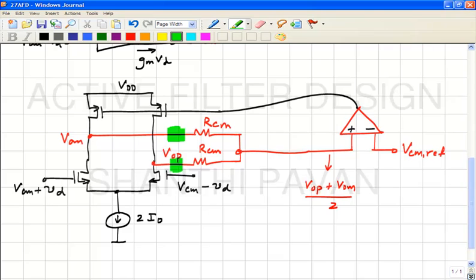Well, there are several problems. One, of course, making a larger resistor means that physically it's larger. It turns out also that whenever you make a resistance, you also pick up parasitics. You can think of this as the chip. The resistor is made in some layer, on top of the chip.